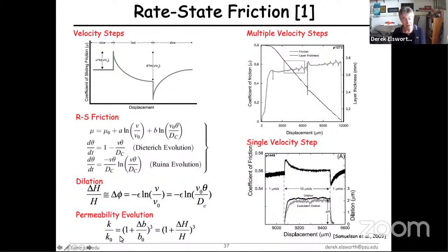But also what you can potentially do, which I think is an exciting area, is try and link the magnitudes of those events to predict exactly what the spatial distribution of permeability changes is within the reservoir. To do that, I think you can use a similar idea to what we've talked about here. We've tried doing it. The idea is that if you can link a change in permeability to a change in aperture, and somehow link the change in aperture to the magnitude of the event that you're recording, then you have an ability to directly predict a spatial distribution of change in permeability with location. And so you certainly can do that.